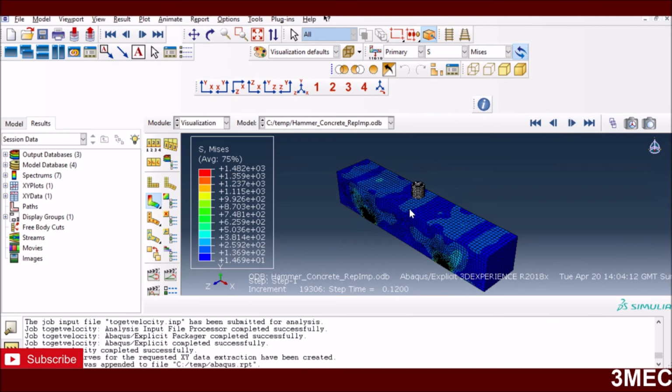Again, depending on how much time interval is between the impacts, these stress waves which are going through your structure may change as well. So again, you have to decide about those times based on your amplitude function. So this is one way of doing it.